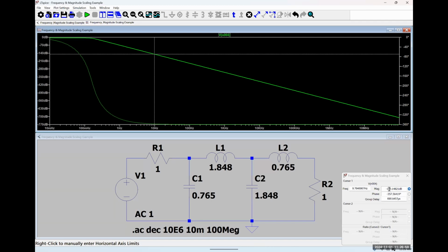So if we had a 5th order filter, it would be dropping off at -100 dB per decade. If we had a 6th order filter, it would be -120 dB per decade, and so on and so forth. So yeah, if we want it to drop faster, or if we want to make that slope larger, we increase the order of the filter. Amir. So it really depends, and also those are going to be active filters and not necessarily Butterworth filters as well.